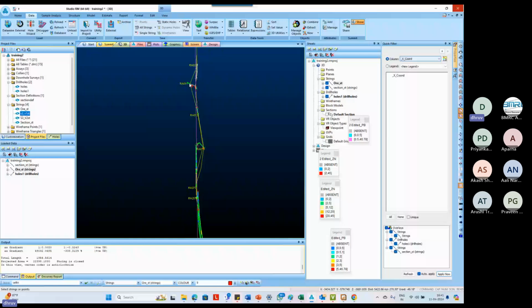If you see this point right now here, if we had done it through a left click earlier, this point would have been on the section plane. But right now it is outside the section plane. Why? Because it tried to smooth this intersection, which is way outside the section plane, so that it comes in smoothly. That's why it has taken a point here, then slowly it came onto the section plane. That is how it should be done, so that there is smoothing in the section, in the third dimension as well. And that will help you to create the wireframe.